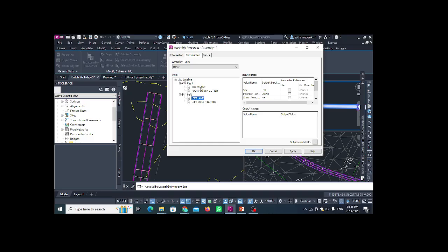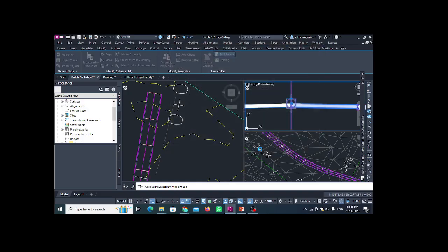So as we imported the transition lane, into this lane you can see the transition here. So you have to set the transition like I have to hold the grade and only change the offset. Okay. The same way here in the left lane, we have to set this part. I will show you. Hold grade and change offset. Okay. Apply. Okay.